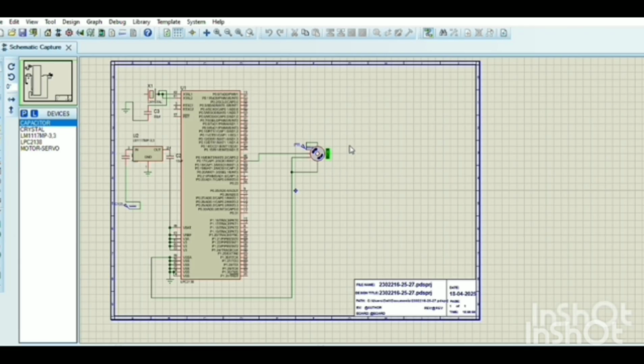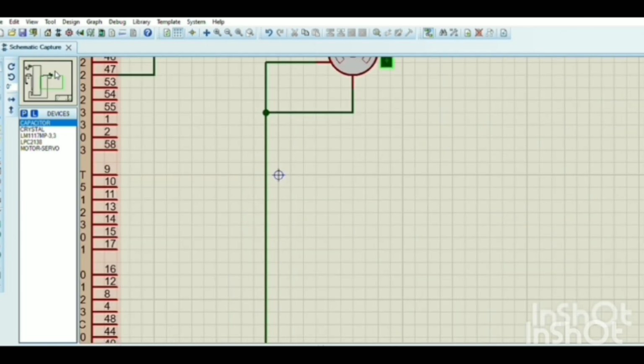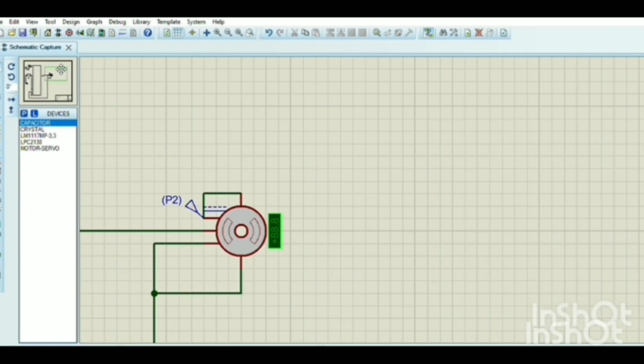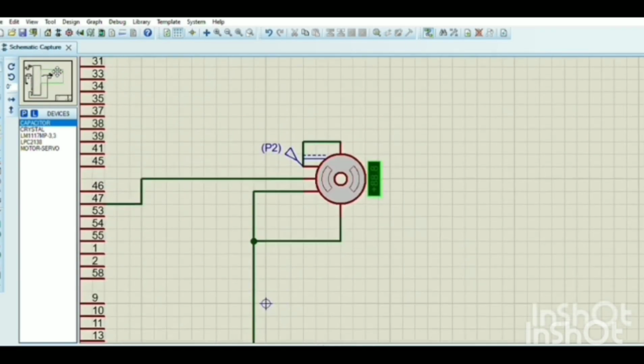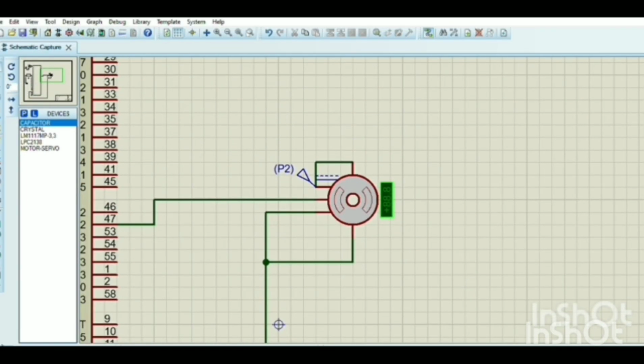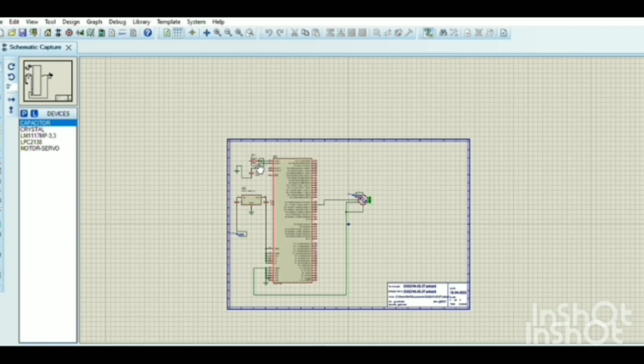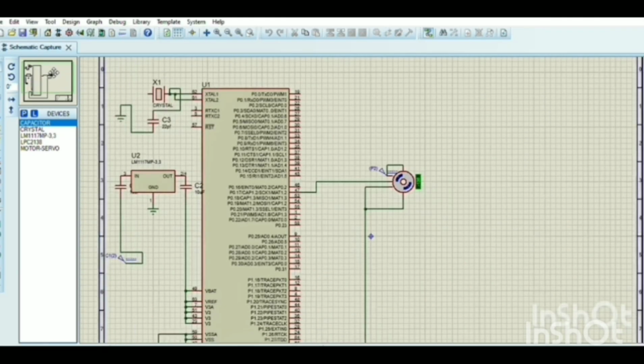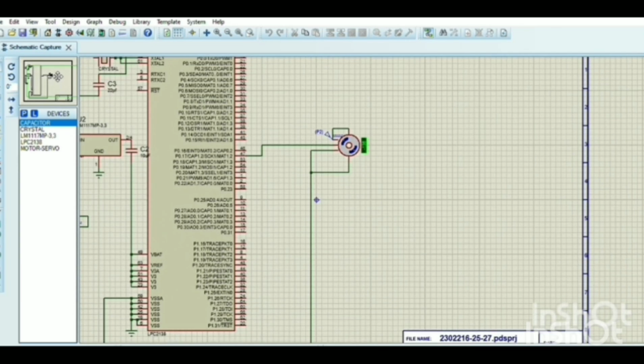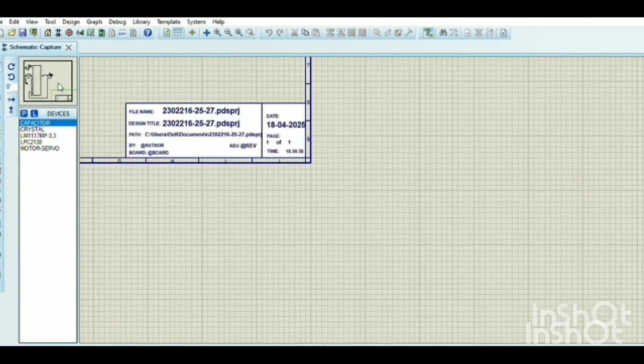It runs up to minus 136 degrees, which is the anti-clockwise direction. I will zoom in and show you for your clear reference of the output. Now you can see it clearly. The servo motor can run up to 160 degrees in real time, but due to Proteus limitations, it runs up to 136 degrees here. Hope you're clear with the connections and how it works overall.